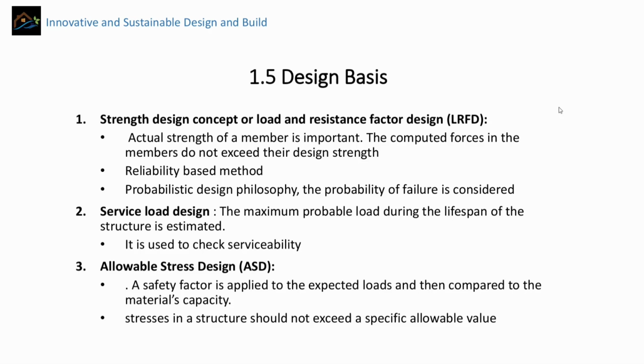This design philosophy comes from the fact that the actual strength of a member is important, and the computed forces in the members that we calculate in each element of the building should not exceed the design strength. This design philosophy is based on reliability, and we use probabilistic fundamentals and concepts in order to calculate the design strength as well as those forces computed in a building element.